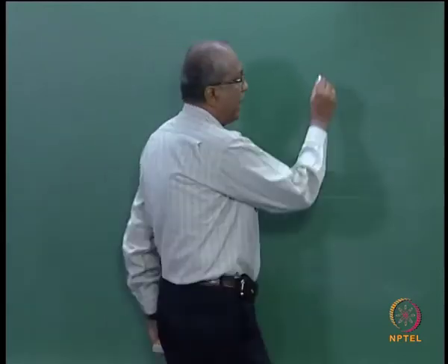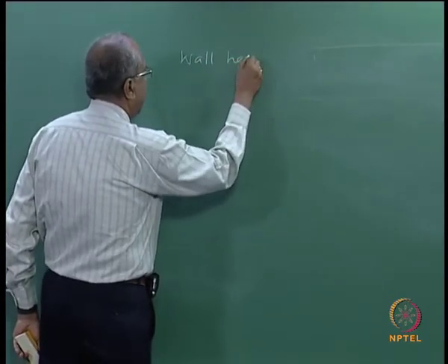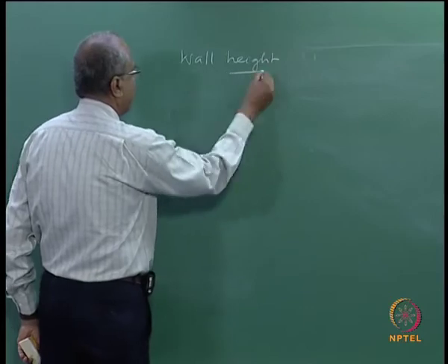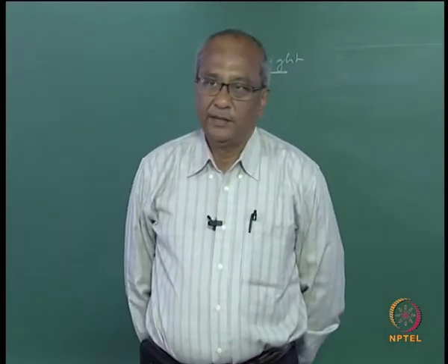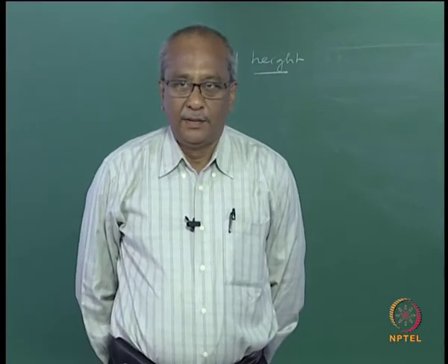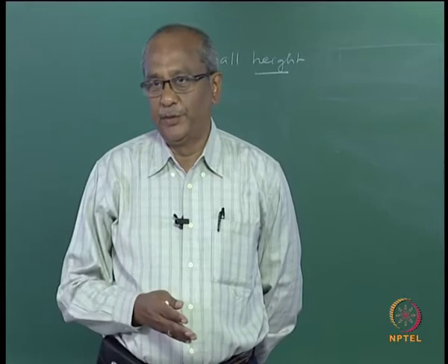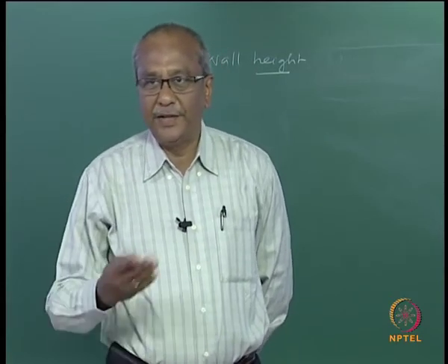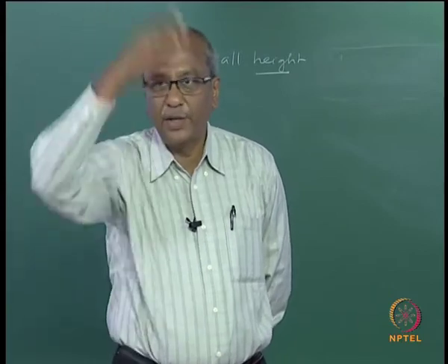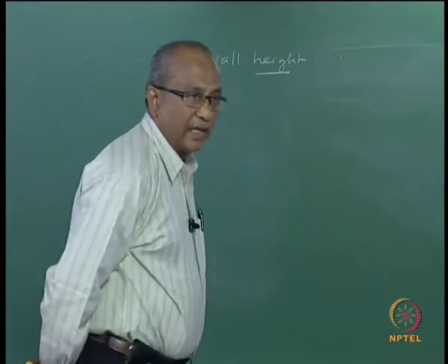So what is the wall height? Do you need the wall height, or do you fix the wall height after the forces are evaluated? It can be either case. You have a wall, you need to evaluate the force. The other case is you evaluate the forces and then calculate your Yc and then fix the top level of the wall. Is that clear?